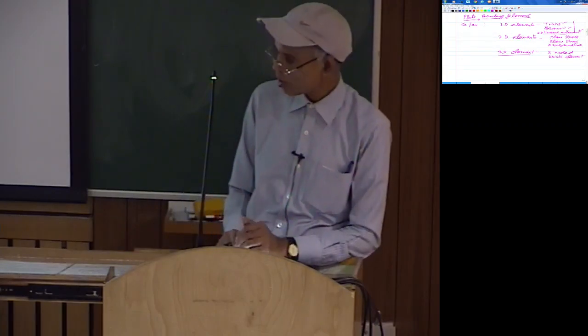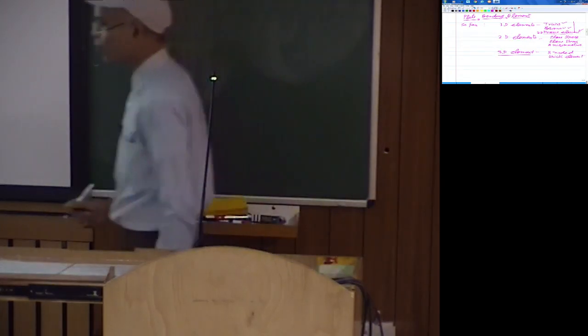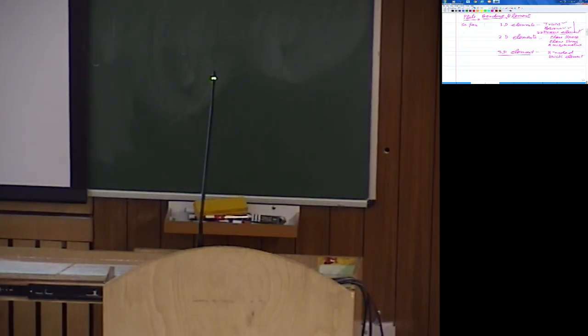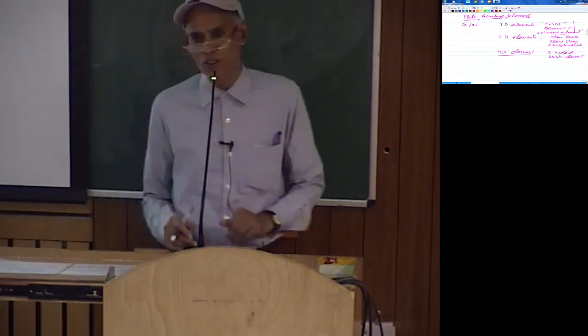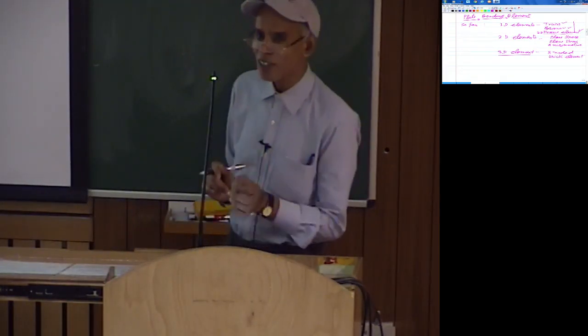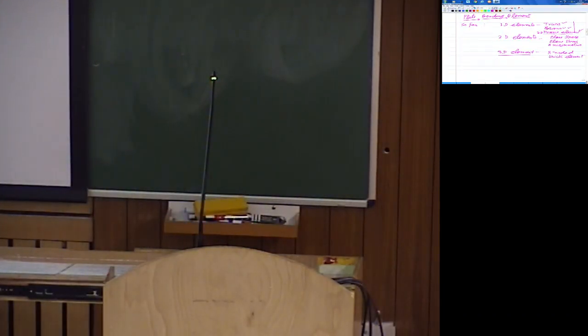But now if you think of a situation, for example, a plate like this, where this dimension and this one are much larger compared to the thickness. You can still model this using 3D, apply whatever loads are there, and solve it. But to capture the bending deformation under a transverse load, maybe I have to use 8-noded elements, maybe 4 elements along the thickness. So one element edge length is going to be very small, and 10 times of that would still be a small number.